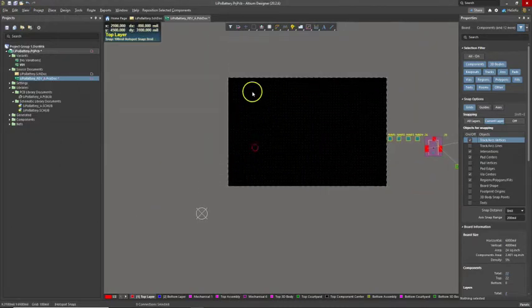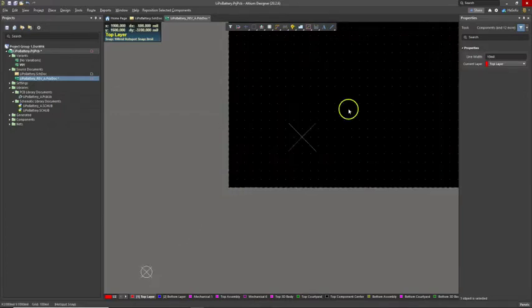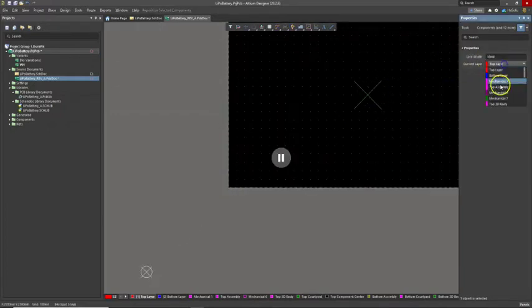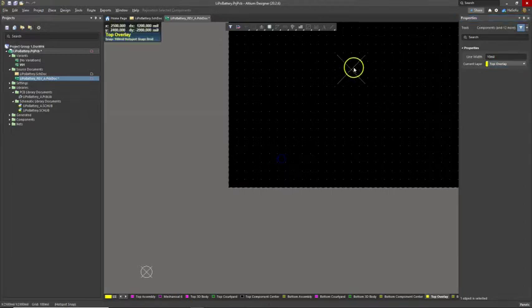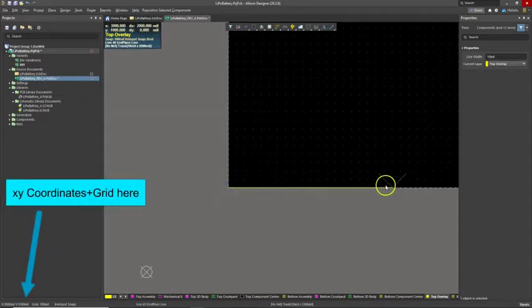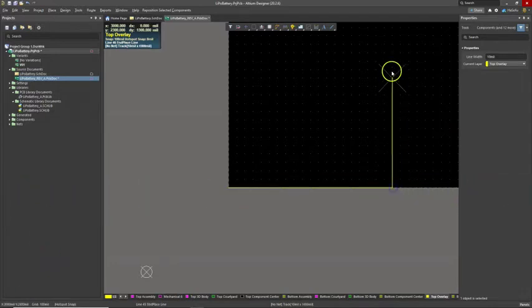All right. So now that we're on a 100 mil grid, which is great, I'm going to place my line and hit Tab to make sure you set this to the top overlay layer. Top overlay is a generic layer you can put pretty much anything on and work with. Now, let's place the line. So I'm going in the 3000 mil direction over here. So 3000. Great. And then click once and then click again.